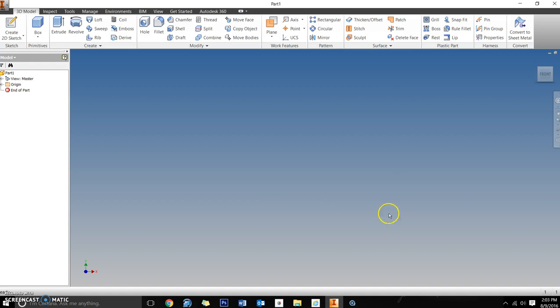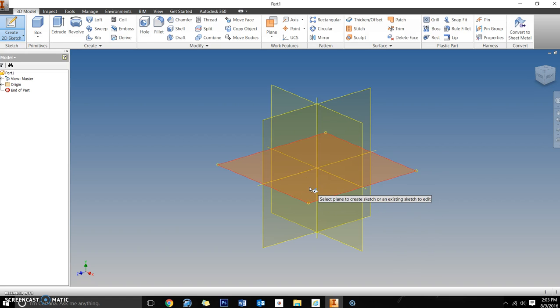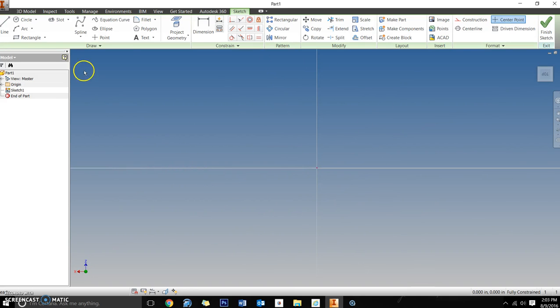We're going to create a new part file and a 2D sketch, and I like to create the sketch from the top plane here. I think it's the XZ plane. I'm going to select that, click on the circle tool, click on the center at the origin, and create a circle. If you remember from making the actual board, the squares that get laid out are 15/16. So these pieces cannot be any larger than about 3/4 of an inch, maybe 7/8.